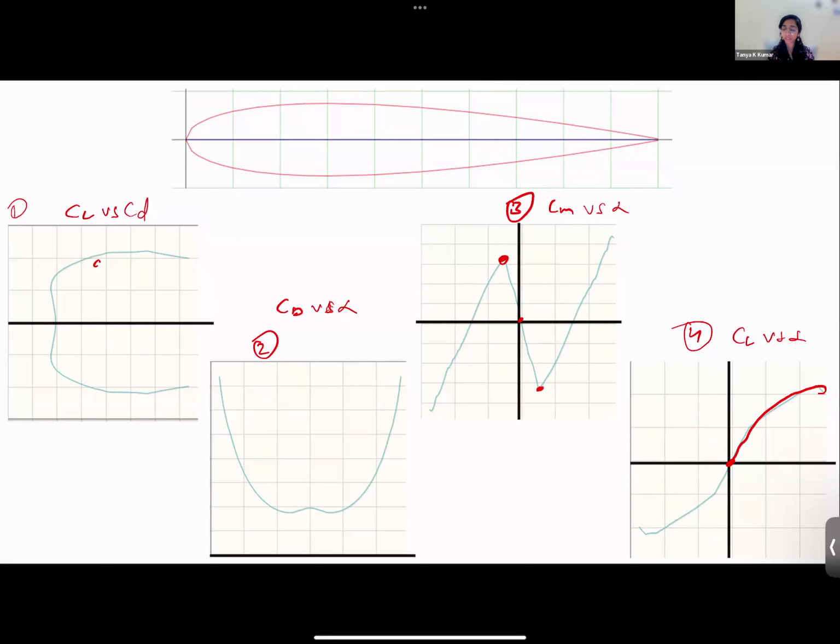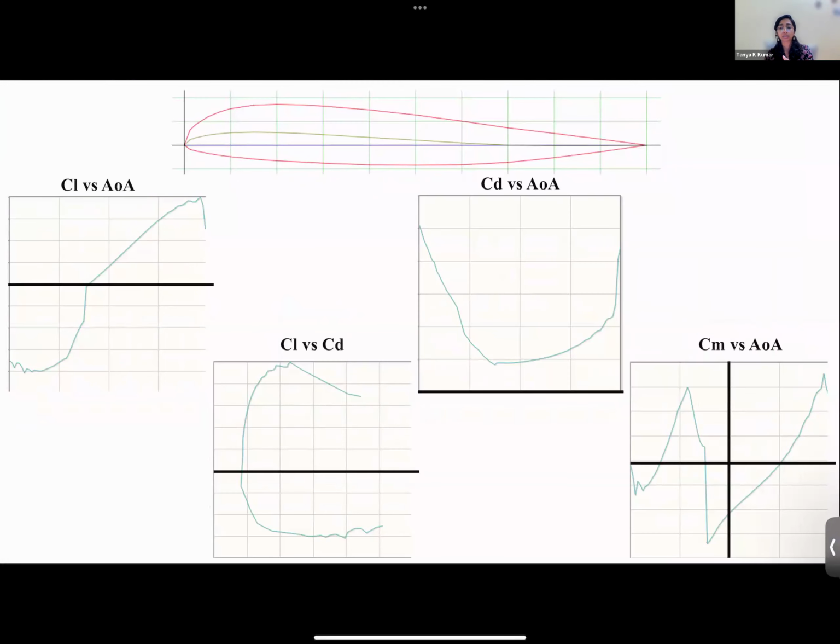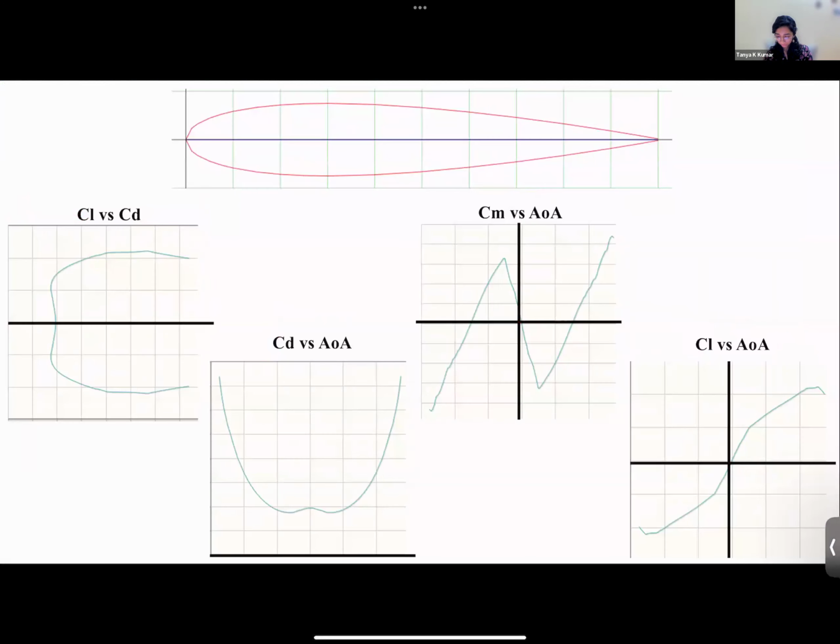Boundary layer separation happening sharply at those points. So that is kind of where the stall happens. This graph is not to scale, but it's where the flow separation happens. The boundary layer is separated, and at that point, there's a sharp change in the pitching moment observed on the airfoil. It's not symmetric in the case of the cambered airfoil, but it's very evident even there. All right. Okay.